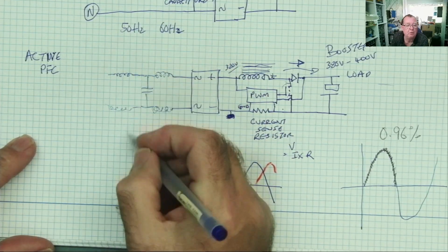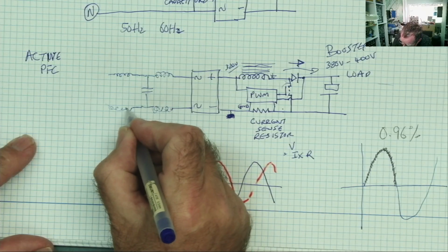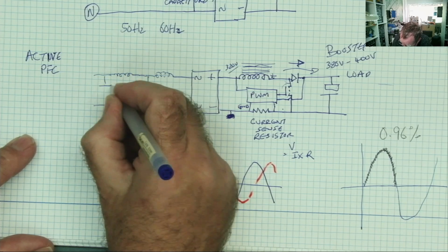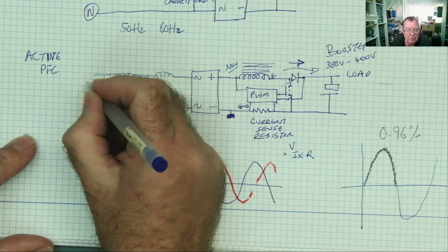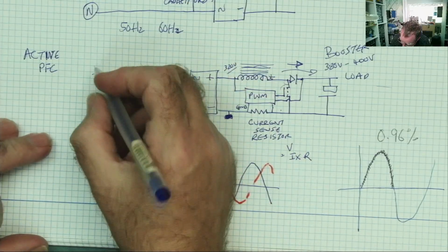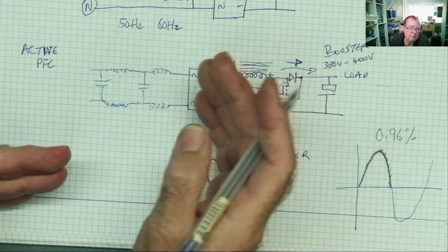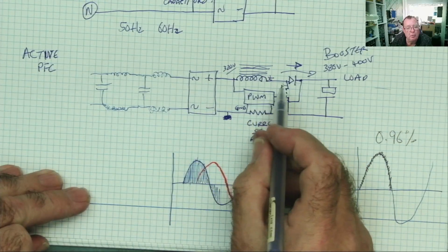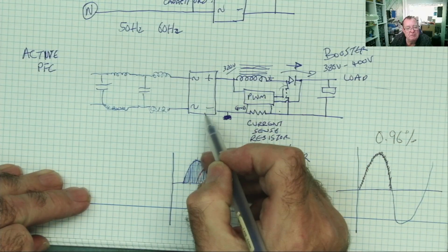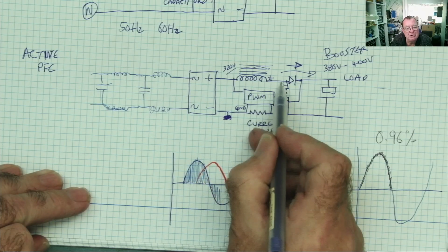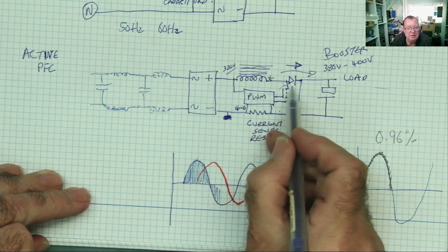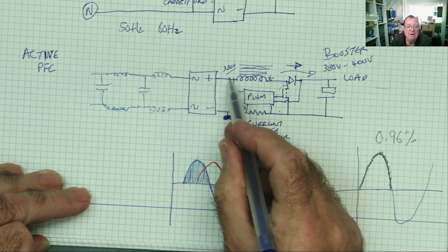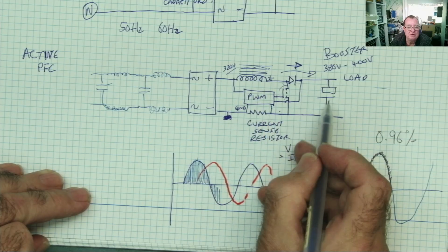These are double inductors, so they're like one in the live, one in the neutral. Another capacitor here. And then this is your live and the neutral through a fuse and an NTC normally. NTC to stop the current rushing in to charge this capacitor. Because even if this PFC isn't working, look, positive and negative, as far as DC is concerned, that is just a short circuit. So even before this is running, or even if this is not running, we'll still get the 320 volts coming in and charging this capacitor.